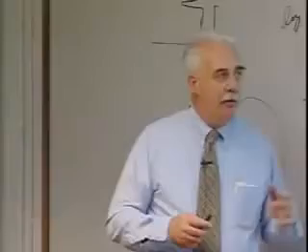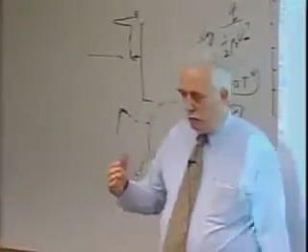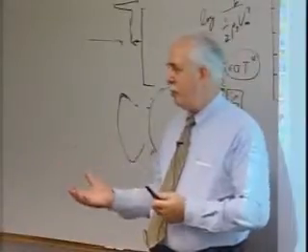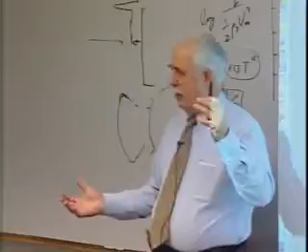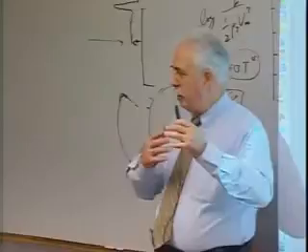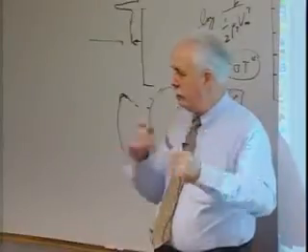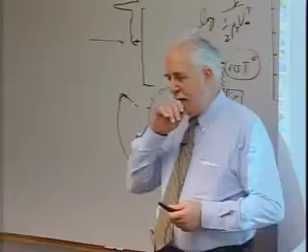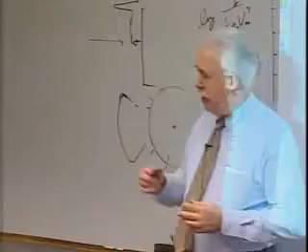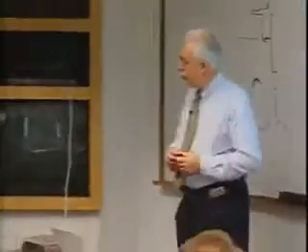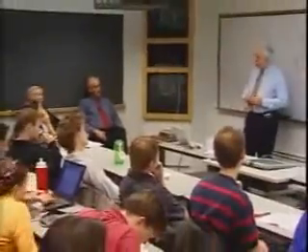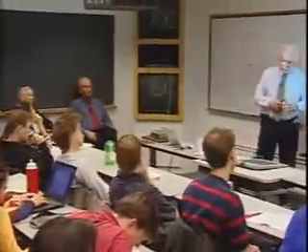On lunar return, it's a problem. However, if you look at the radiative heating, it's first order proportional to dimension, whereas the convective heating is just the opposite. It's inversely proportional to the square root. So as you go up in dimension, your convective heating is less important, as we did with the shuttle, and I'll try to address that in a minute. So we don't really have the ablator type of material that would work for Mars return? I think we could develop an ablator, but we'd have to do it in an environment that gets as close as we can to simulating the radiation. And these days, there's a lot more capability there than there was in Apollo days. But that is a real challenge.